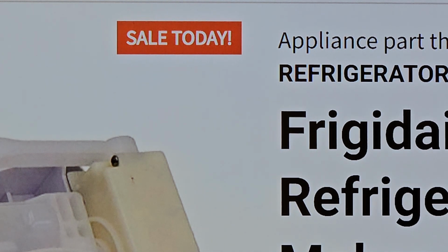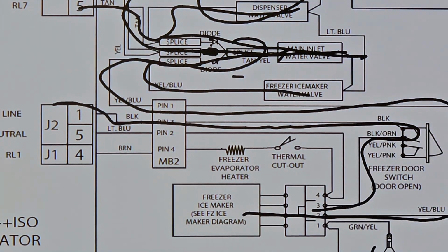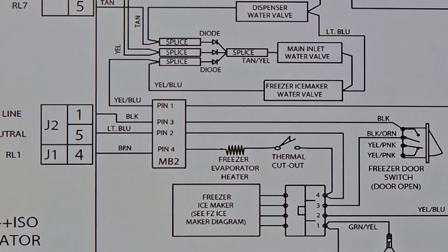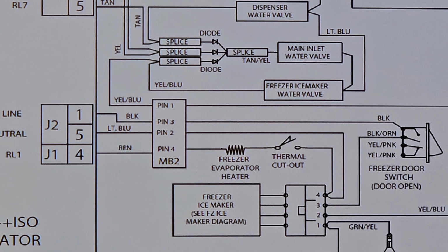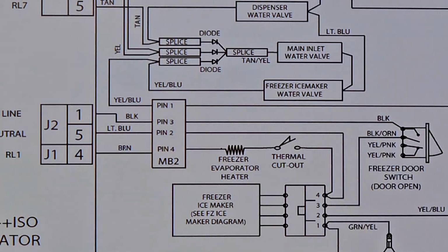Now, this works off of what? Temperature. Oh, now we've added more problems to it. Because now, if we look at this ice maker, the ice maker has its own evaporator. Has a fan back there. It has its own way of making ice. Where's my pen? Oh, here. Okay, so where is that evaporator fan for the freezer? On the low voltage side? For the ice maker, okay? So where is it? This is the ice maker fan, right?